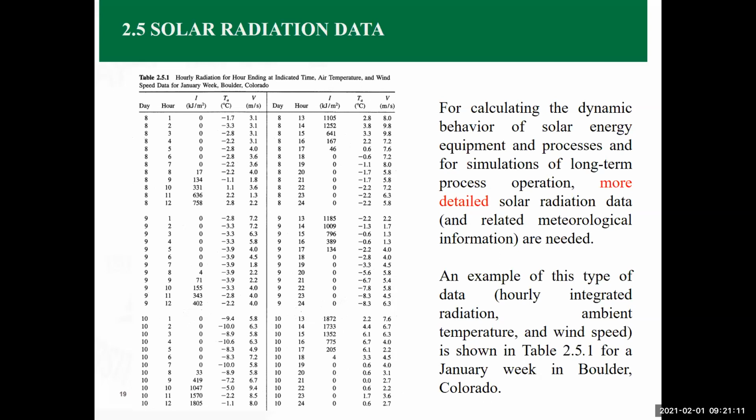After that, in the next batch of air conditioners that were bought, they changed it to air conditioners dealing with a nominal design temperature of 105 Fahrenheit, which made more sense in the way that it provided comfort for most of the year. So the same thing here. If you know the data that you have, you can make your decision of what kind of devices or equipment you need to buy based on the values that you have.